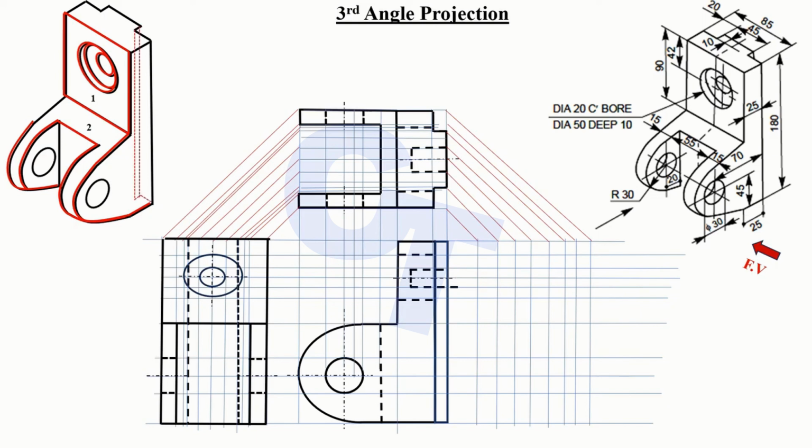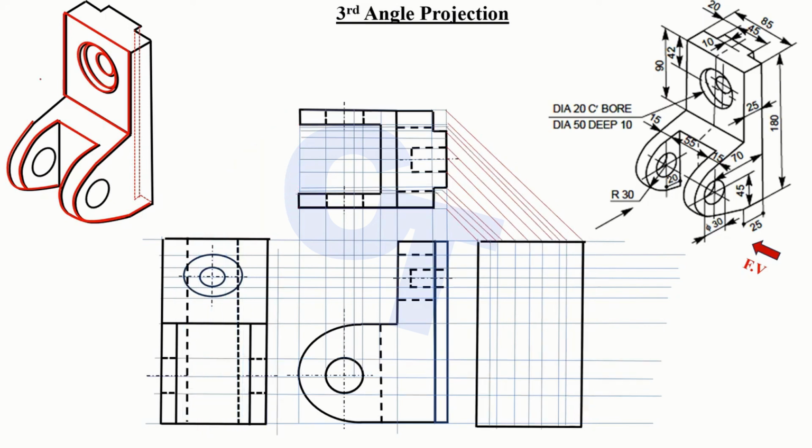So right here, first of all, we're going to see a box, right? As you can see, that's what we're going to see. So I'm not going to see this layer right here, but it is there. And we're going to indicate that using hidden detail, and we're getting the measurements from the plan right here. Okay? And what we're going to see now, these 2 lines, we're not going to see them. And this circle, the big one, I'm not going to see it, right? But it's going to be there, so I'm going to draw that circle.